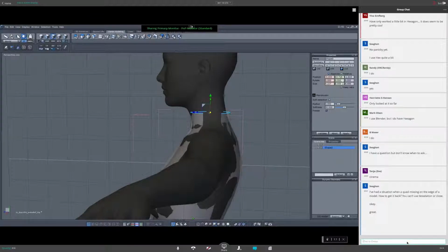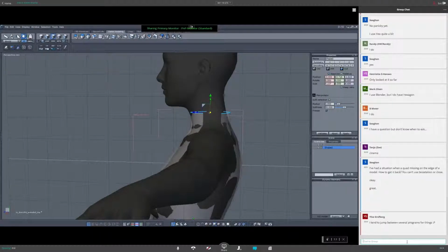And if you want to have something of an even size, you pick your appropriate column and enter the number 0. Keep ratio is different. If you check this, all the axes will be influenced and scaled in relation to each other, so I wouldn't recommend this. Just leave this. Okay, now we have a completely straight edge of the collar in relation to our modeling document,